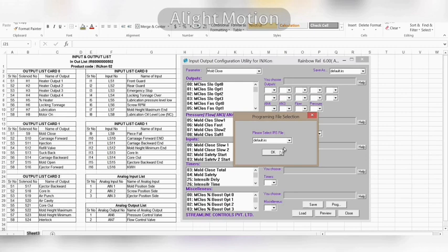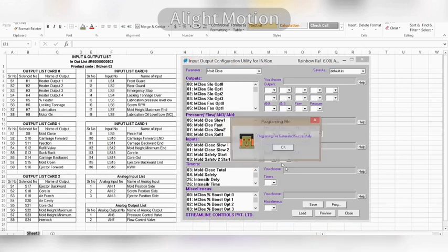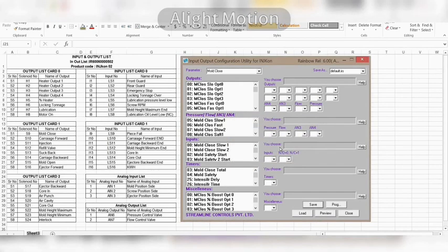If your sequence code is not in it, and you are creating a new sequence file, then you will have to go to Save As and change the file name. You can see that the sequence code of my wiring list is not in it. So I loaded the old file by default .irs. Then I will go into Save As and type the sequence code of my file.